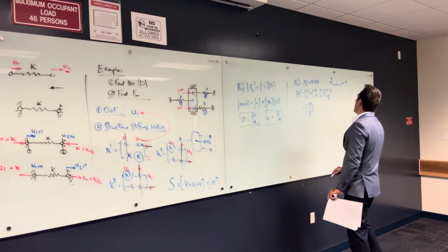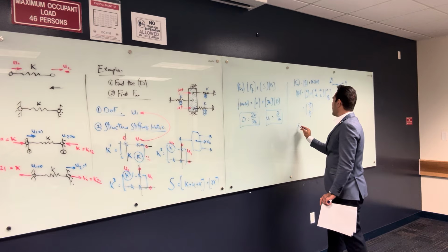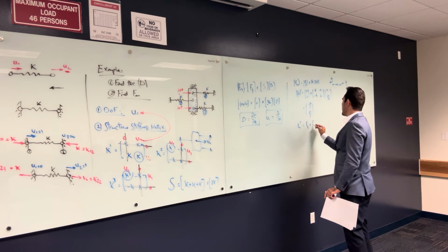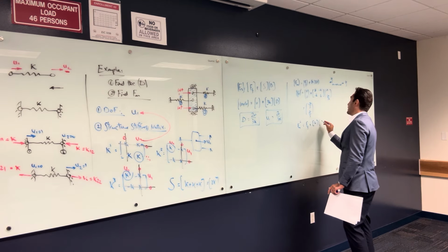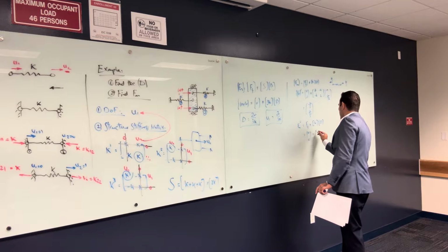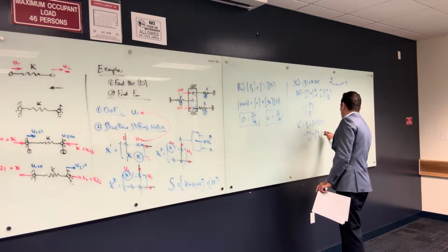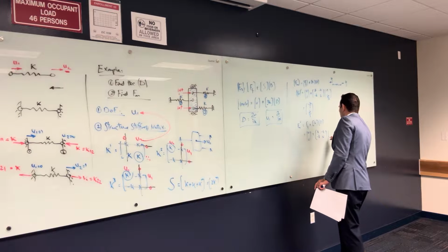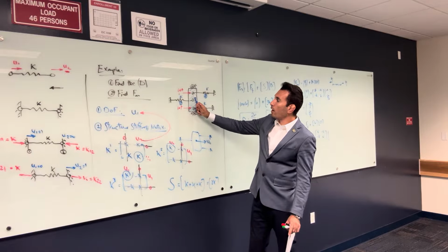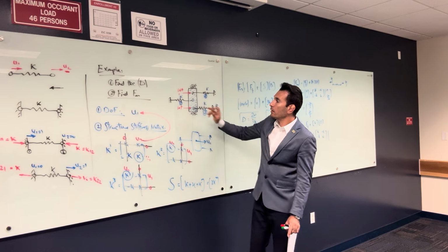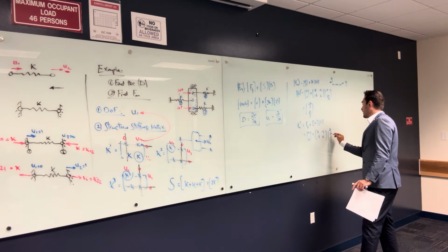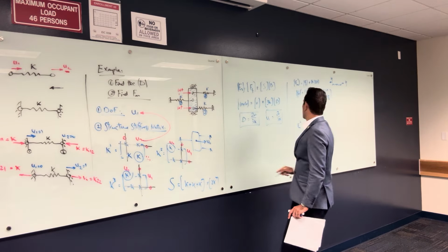Let's get force number 2. F member 2 is going to be equal to the fixed end forces plus the stiffness matrix multiplied by the displacement vector. So zeros plus K, negative K, negative K, K, multiplied by U. All right, so the displacement of member number 2, can you guys tell me what is the U here? U1, which is 20 over 3K. How about the displacement here? 0.